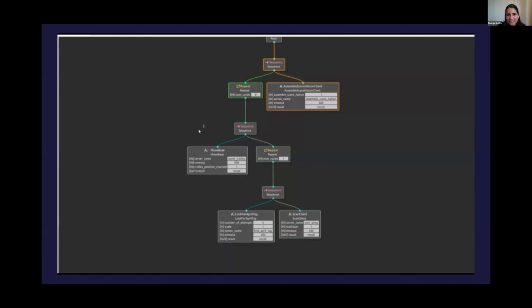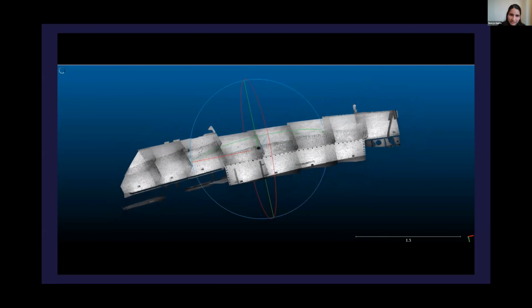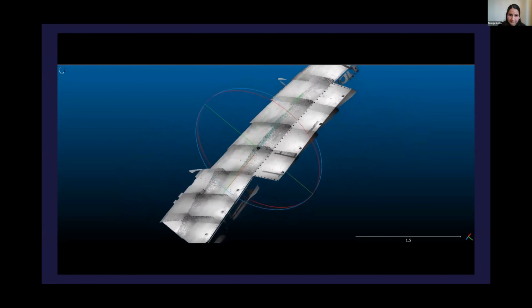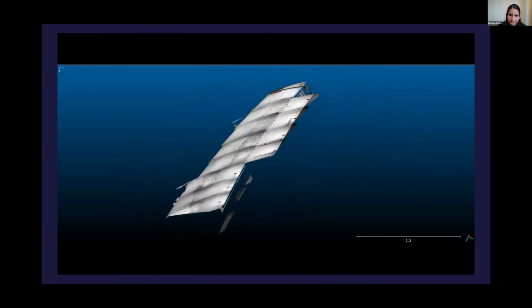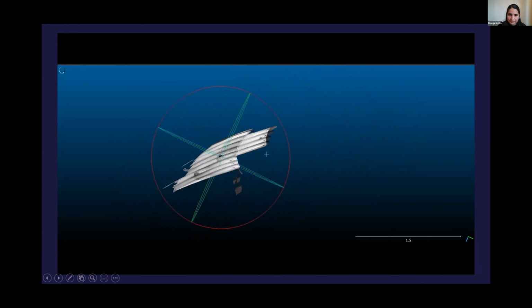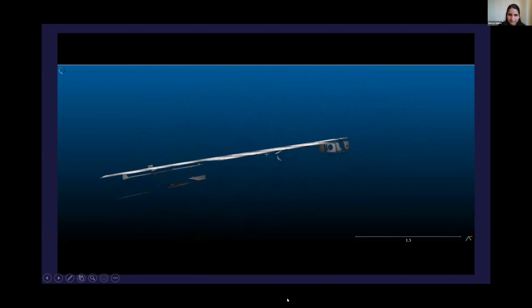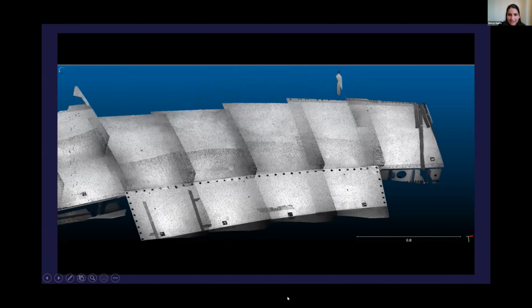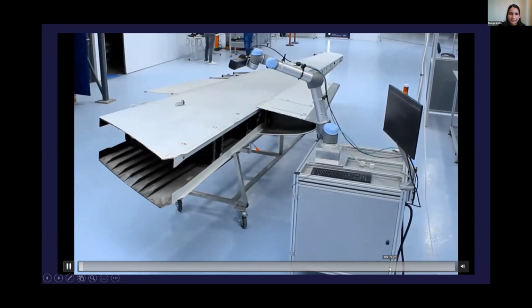And then it passes to the assembled scan. These are the results. So you can see the Z alignment and stitching accuracy, there are no misalignments with respect to Z that we were facing with the ROS assembler method.